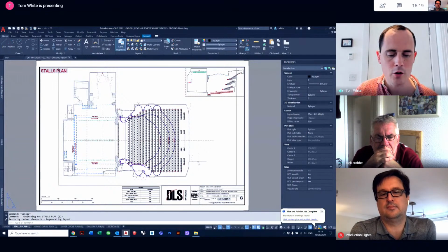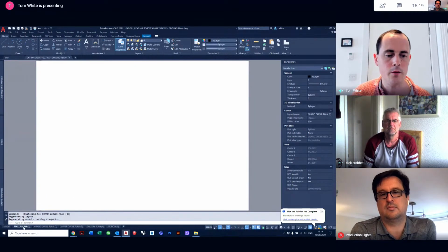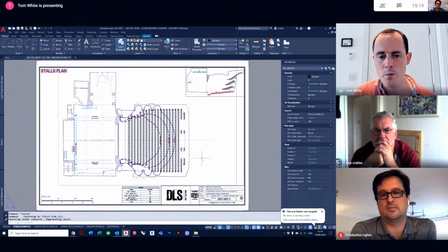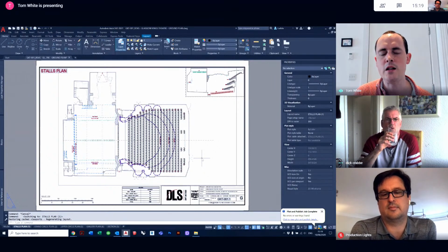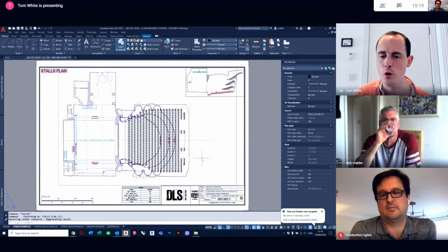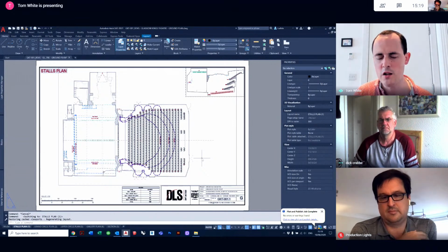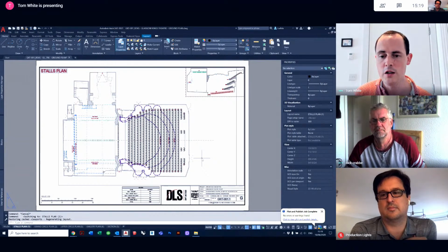You can, as we talked about, do Control P to print this PDF, and you could print it 5 times. So you could, in the first one, print page 1, page 2, etc., which is a very, very sensible way of doing it. There's a feature that's been in AutoCAD for maybe 3 or 4 years, which again Dom might be able to tell more specifically, that will plot a DWG to a PDF at a certain state within your process. Those states are when you save your drawing, you might desire to do a PDF. When you close the drawing, you might desire to do a PDF, and there's a couple of other circumstances.